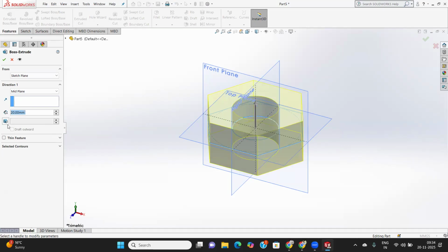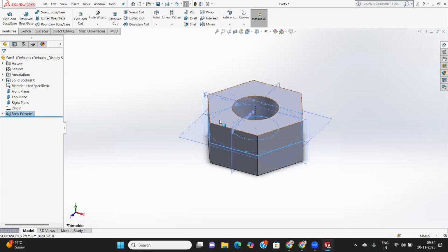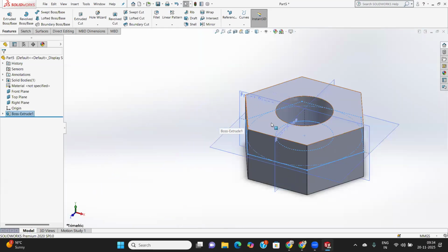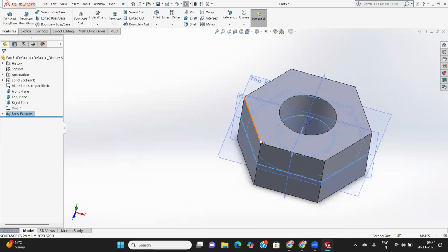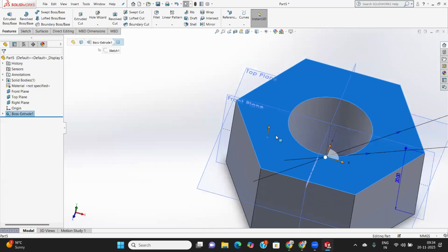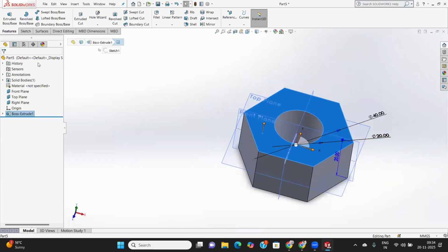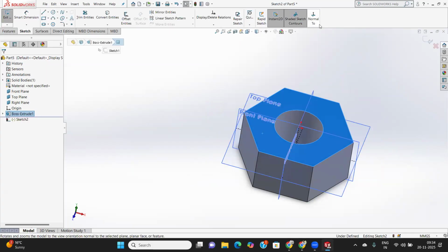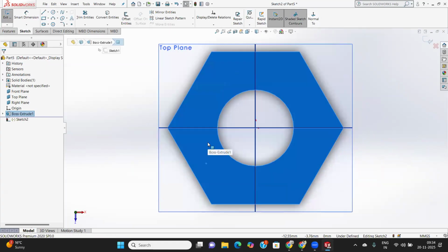What I want to do is make this look like a nut bolt, but in this case we have the chamfer. This portion is my chamfer right there. You need to see that in the nut bolt, where this point is the chamfer. Then how can we make the chamfer? For this part, first of all select this face, go to the sketch module, click on the sketch module to normal to, and then I want to make something right there.